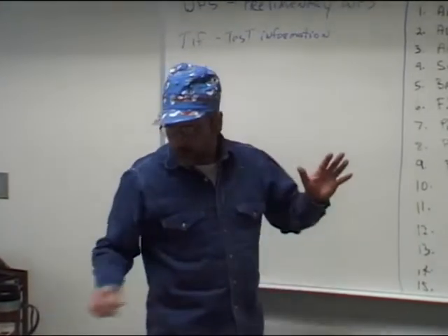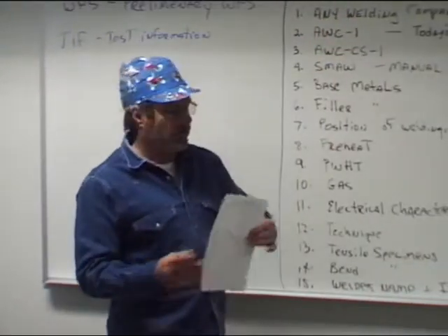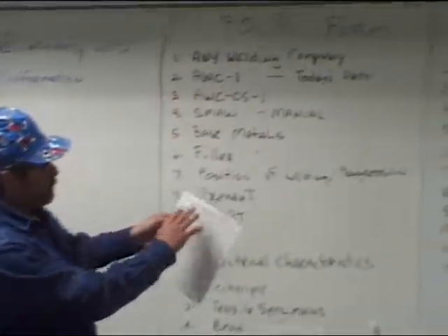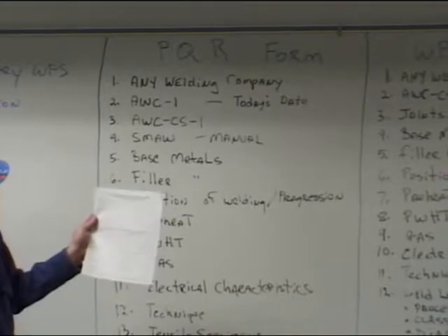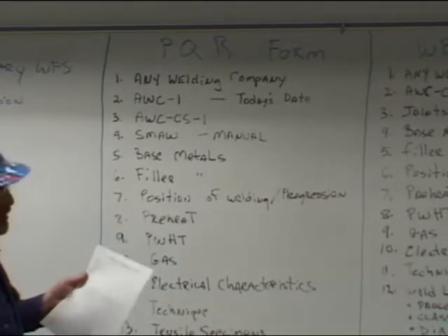Then we go from that to the PQR, which is this form, and the one I've asked you to pull out. And this is where we fill in the blanks with all the actual information that was used in the welding of that test specimen.